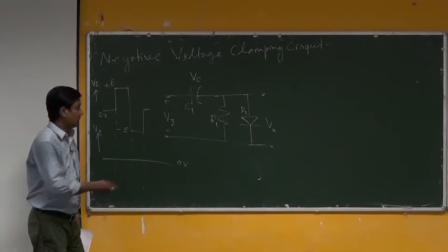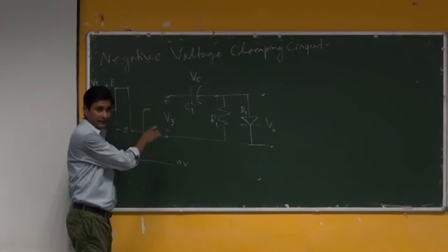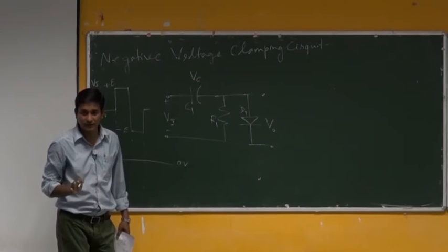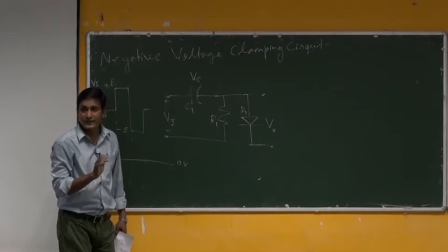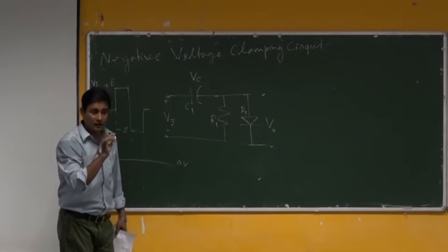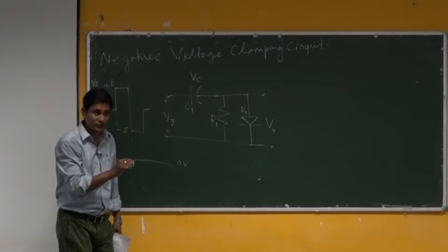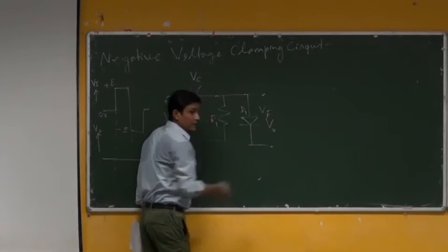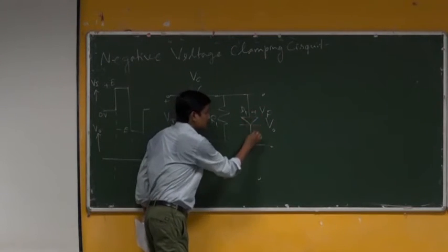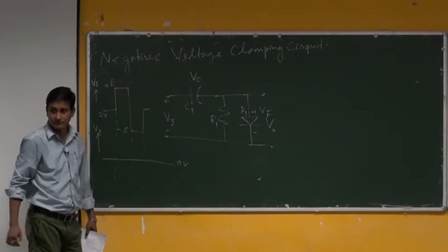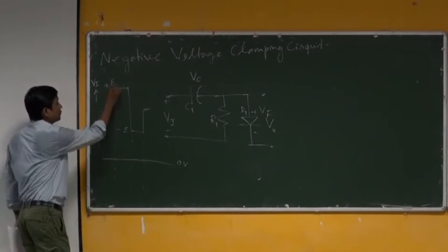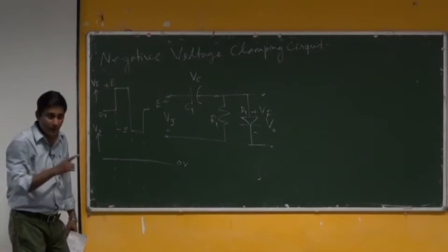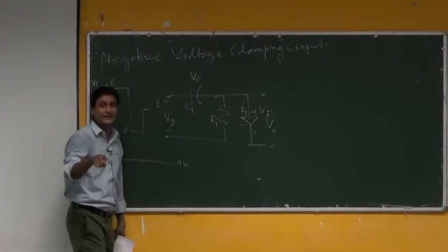Okay. So, say the input voltage which is applied there has gone to this diode which has made it forward biased. It is a simple diode, not Zener. So, it has a forward voltage Vf across it, because the constant voltage drop model is used there with Vf voltage. If it conducts, then Vf voltage will be coming here with what polarity? Plus, minus. Now, if the voltage has gone from 0 to plus E, that means plus E volt has come to the input. Some part of it has gone as Vf there to make the diode forward biased.